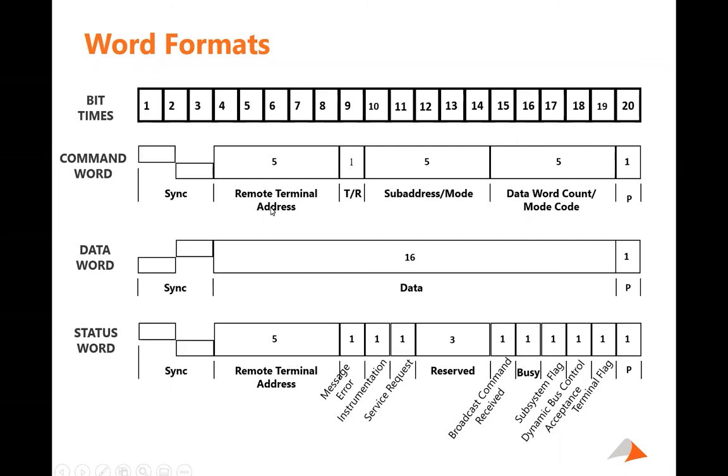And that's basically how the word's decoded, now that you've got the time encoded in with the word itself. The next 5 bits are the remote terminal address. Every remote terminal has an address. In many cases, the address is hardwired from an external port on the system itself. Other times it's software defined, so that way you can change it on the fly if you need to. Most systems, once they're in place, though, that's what they are. They're not going to be changing unless, of course, you're adding stuff and you need to change things around.